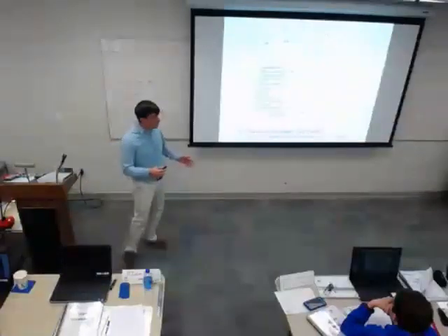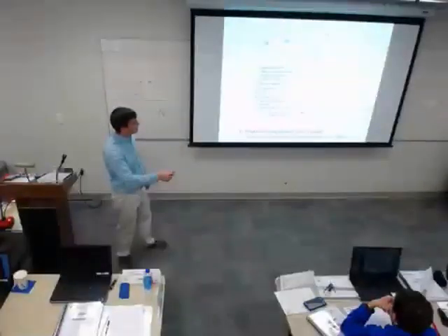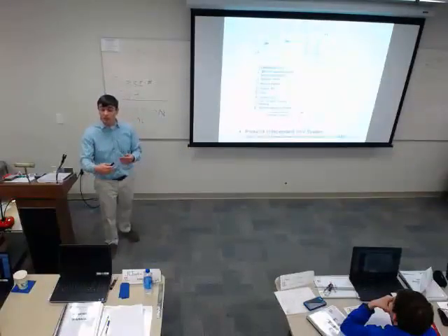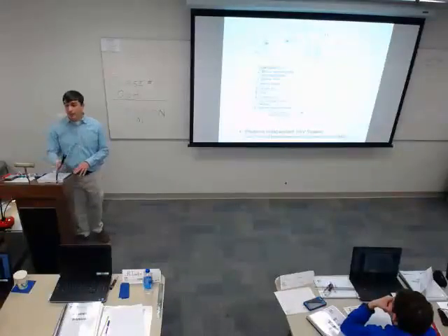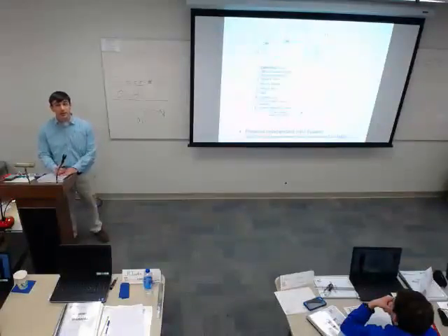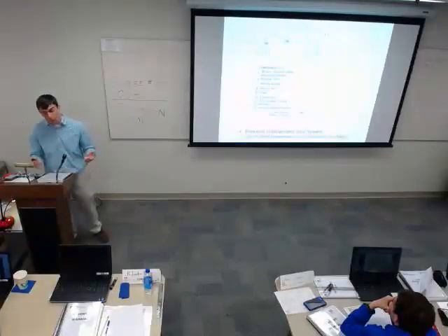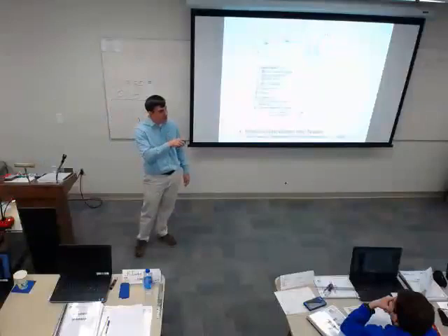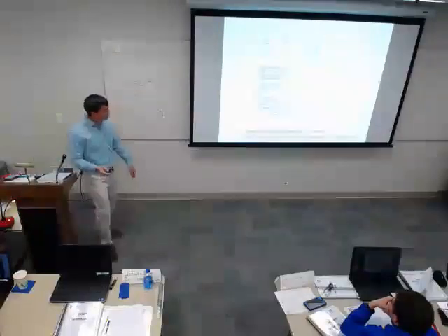Just going back to that whole static pressure, that's a good question. Right in line with this, I can measure. Maybe they got the wrong kind of filter there. Maybe they gave me too good of a filter beyond what I called for, and there's some extra resistance there. I probably got a lot of construction filters. Could be. Who knows? We had a cash register end up in a duct system one time because the dining facility next to us got broken into, and they literally threw the cash register into our duct system. So you never know what obstructions you might have in your duct system. That's a true story.